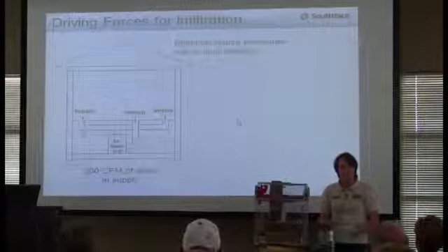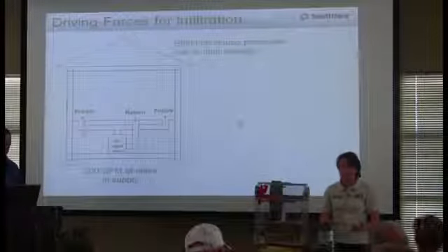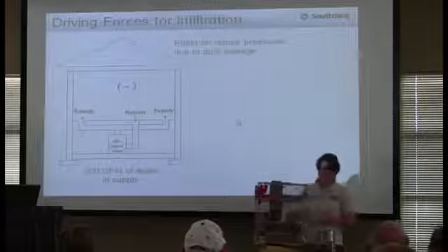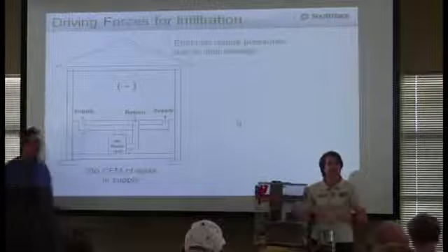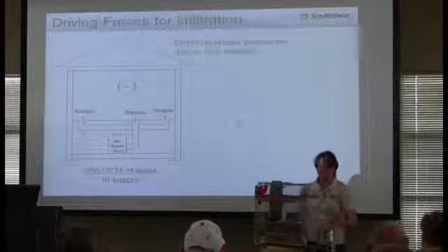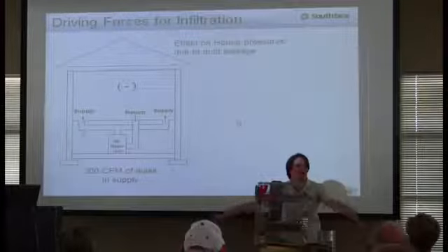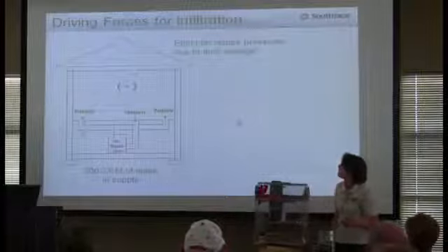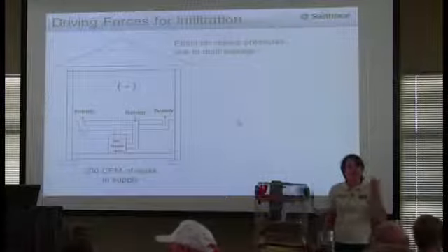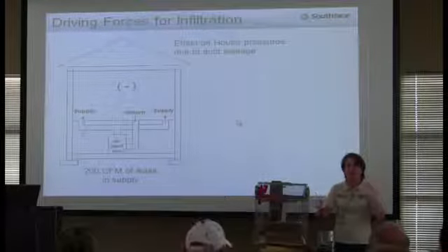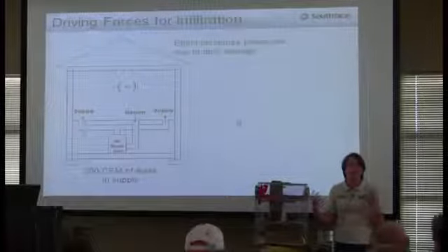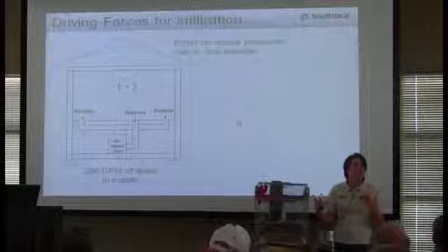is this house starving or bloating? Starving. All right, so let's see. You see how the center of the house is going under a negative pressure because I just gave you some supply leakage. We can also see the crawl space is now at positive pressure, right? It's getting 200 CFM. So what we like to say is supply leaks suck. It's kind of counterintuitive to our brain, right? Because we think a supply is always pressurizing a room. But that's not what happens when you're leaking.